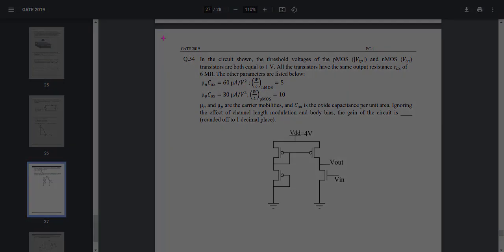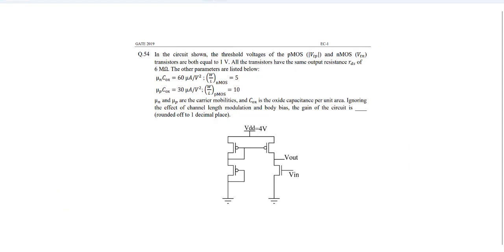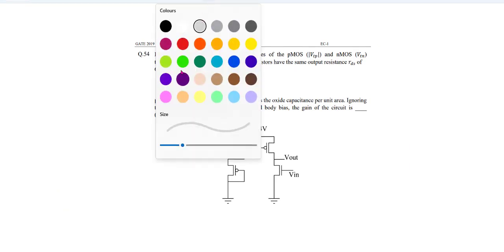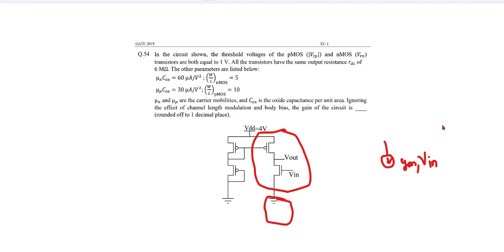Now you see that this part here is nothing but a current source, gm1 Vin, only this gm. If there were some MOSFET present here, then the gm would change, and that we have seen. So this is like a gm and whatever is an RL.